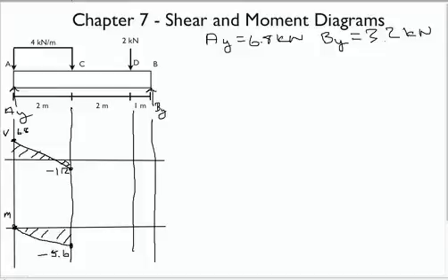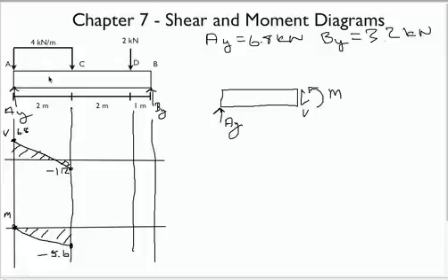All right. So draw a free body diagram. AY, shear, moment. Now, when we've basically gone through AC, the amount of this distributed load that we need to take into account as we make a cut is fixed. It doesn't change anymore since we're out here. So if we're standing out here, just standing on the beam and looking back that way, we see the whole load. We don't see part of it. If we were in here, looking back that way, we'd only see the part in front of us. So we'd only see, let's say, that much of the load. But since we're out here, we see all the load.